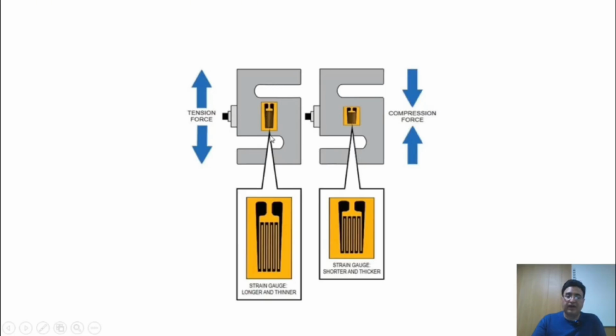The S-type load cell, and at the center of this load cell, our strain gauge is installed. These load cells are generally tension-type load cells. They are used for measuring tensile forces. But in addition to measuring tensile forces, these highly sensitive and robust load cells can also accurately measure significant compressive forces for us, providing comprehensive data. So this particular load cell is a versatile tension compression load cell. It is specifically designed to accurately measure both tensile forces and compressive forces for us.